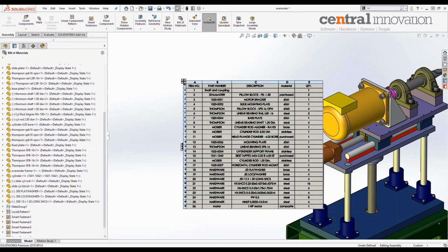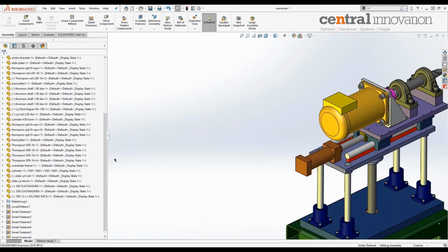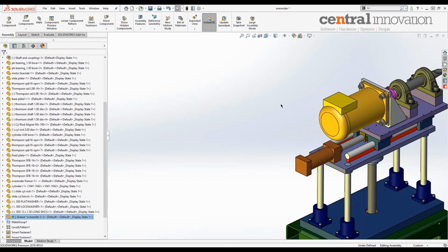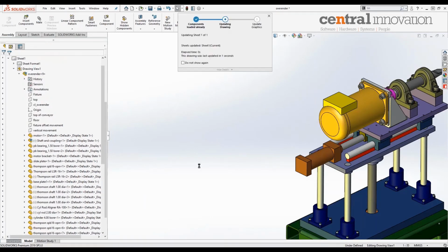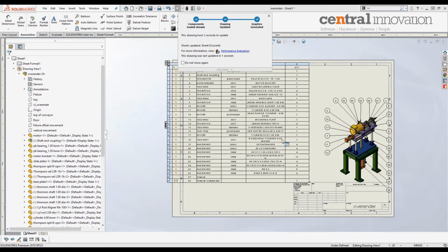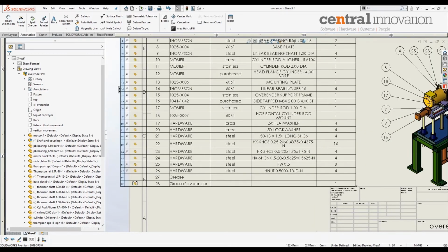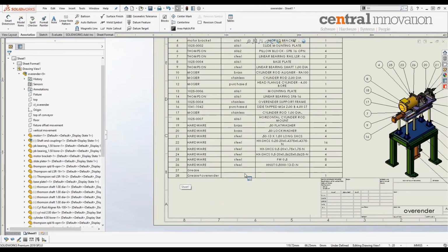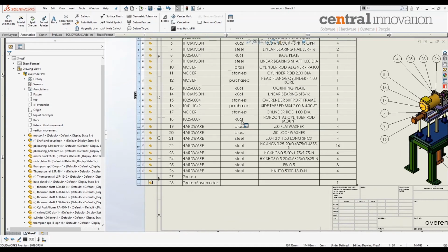However, there is another option. At the assembly level, there's an option where we can create virtual components as well. We go to Insert Components, New Part. When we insert a new part from within the assembly, it actually creates a virtual component, which is not saved in an external file. I'll name it grease. I wouldn't create anything for this one, I'll just leave it like it is. And it automatically lists that part in the bill of materials as well.